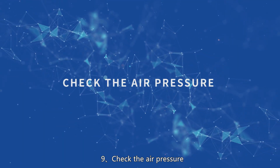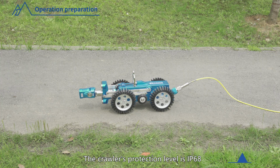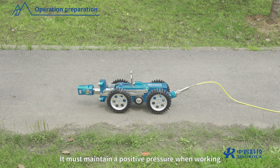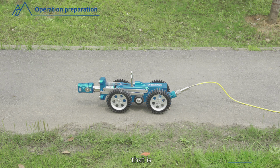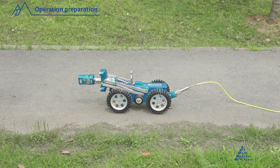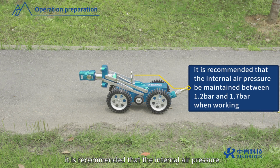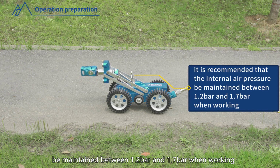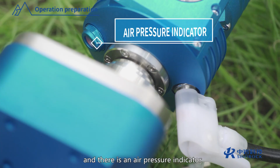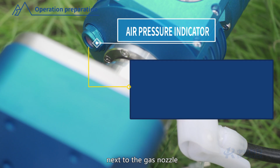9. Check the air pressure. The crawler's protection level is IP68 with a built-in air pressure sensor. It must maintain a positive pressure when working, that is, the internal air pressure is greater than the ambient air pressure. Generally, it is recommended that the internal air pressure be maintained between 1.2 bar and 1.7 bar when working, and there is an air pressure indicator next to the gas nozzle.